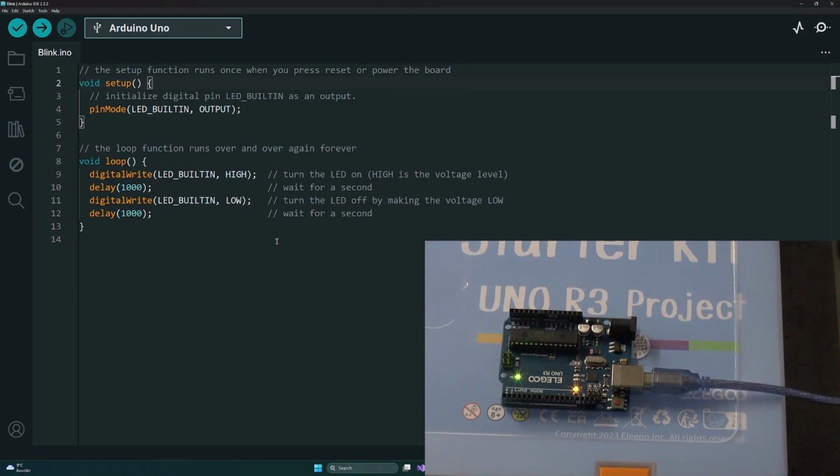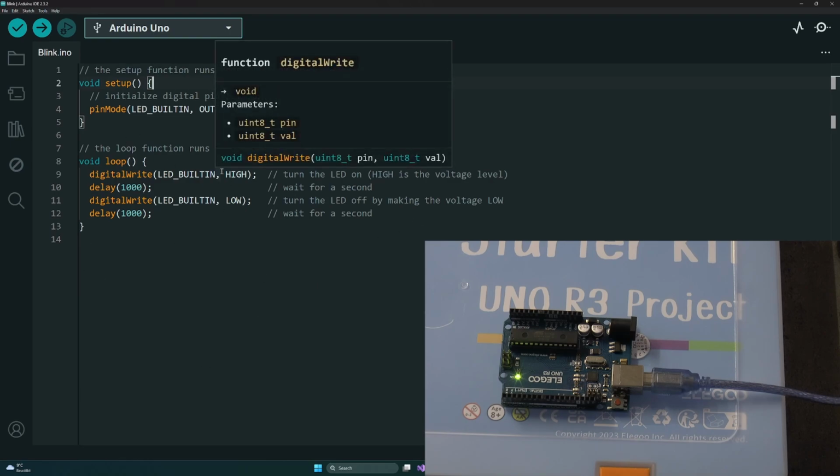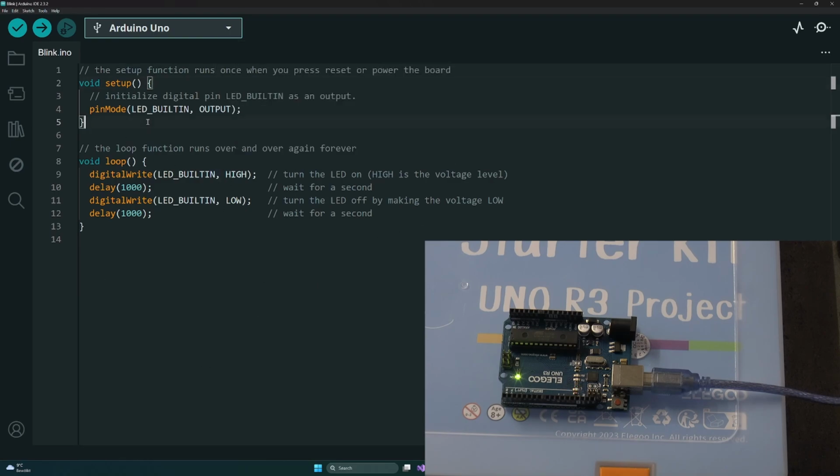And in order that the microcontroller knows what to actually do, you need to first tell it how you're going to use the pin. This is not only so that the microcontroller knows what you are doing, it is also about how to set up the pin. Because a pin, if it's not configured, is kind of floating. Sometimes it's configured to a default state, like by default every pin is an input. But it could also be that the pin is completely floating, so the pin is not connected to some internal circuitries. And only if you're configuring your pin mode, the pin gets configured in a good state.